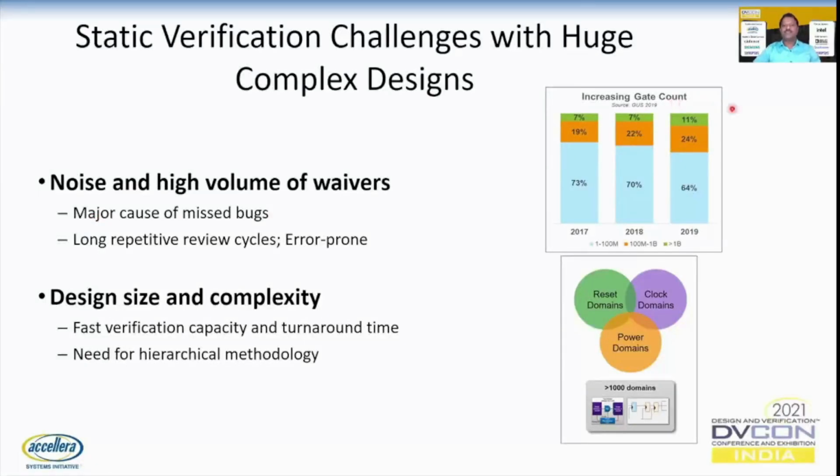All of us know the design size is increasing over a period. Requirements of new features and solutions have triggered an increase in design size. Growth in new features being added to the design is causing project teams to validate the design from various domains of static analysis. Surge in multiple clocks and resets is demanding validation of CDC and RDC checks for each and every design being signed off. The need for performing various domain analysis brings the situation of a huge number of messages, which in turn causes heavy usage of waivers also.